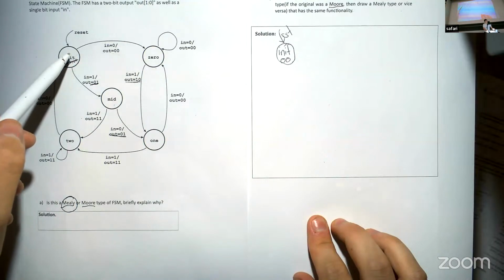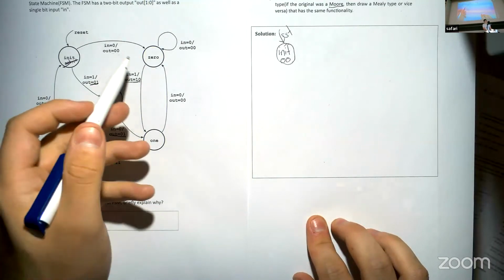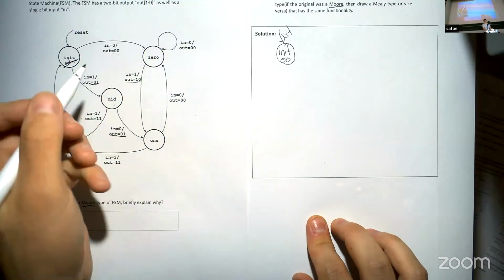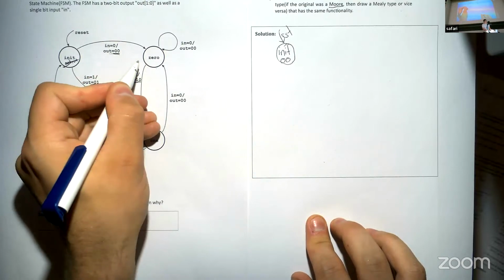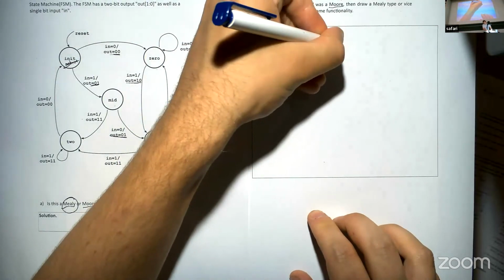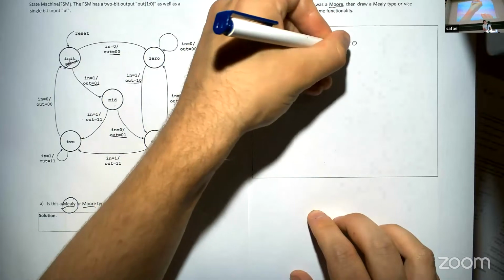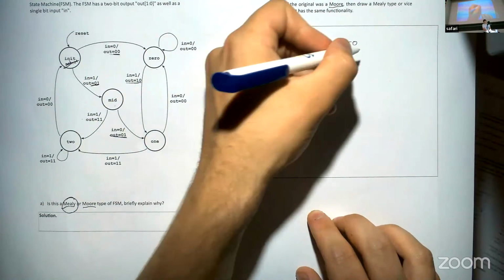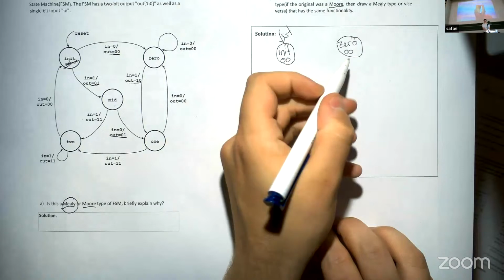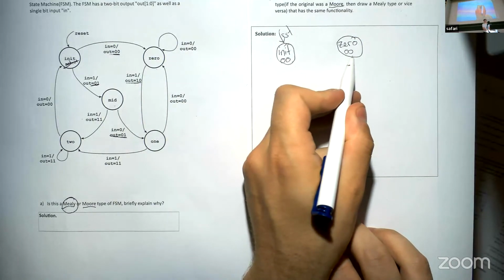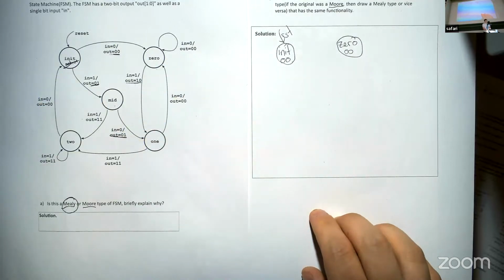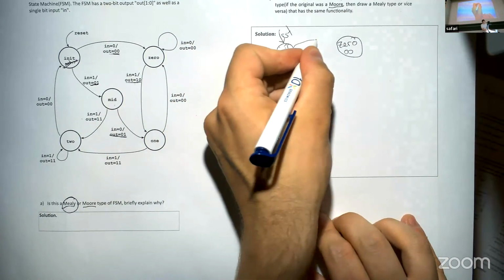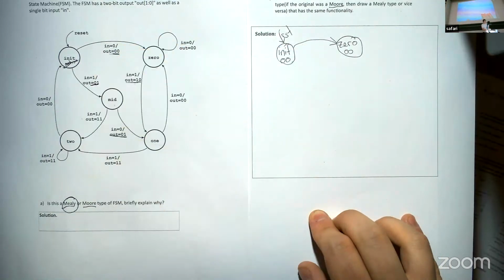Okay, and from here we can go to the 0 state with the output 0, 0. So just to highlight this again, because the output here is 0, 0, we call the state 0, 0, 0. I'm just implying here that this is also the output of the state. Probably in your solution, to be clear, you should write a sentence like, the output in these states is always the second line, something like that. Clearly identify your outputs, basically.